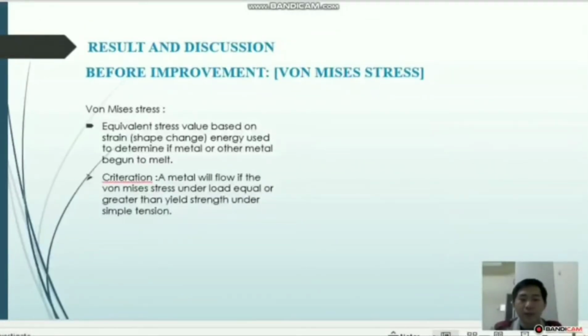Hello, good morning. My name is Geraldo Ispirin. I want to present my part, which is the result and discussion before improvement of von Mises stress for each part of our project. So the first one is, what is von Mises stress? Von Mises stress is an equivalent stress value based on strength, shape change, and energy used to determine if metal begins to yield. And what is actually the criterion? A metal will yield if the von Mises stress under load is equal to or greater than the yield strength under simple tension.